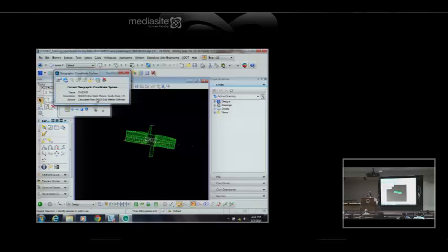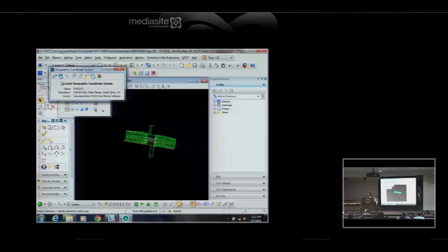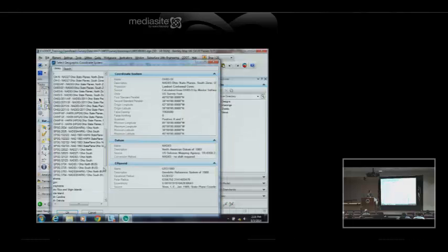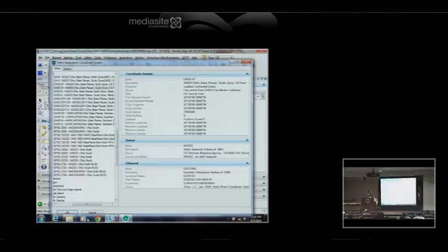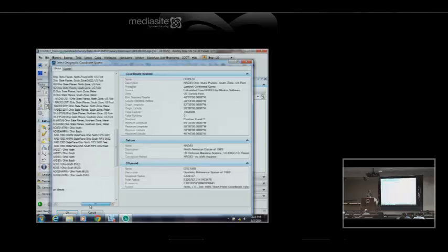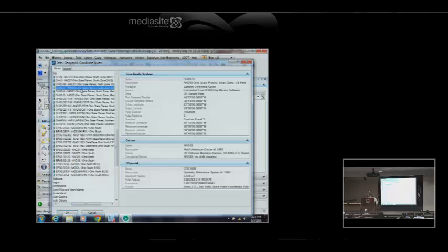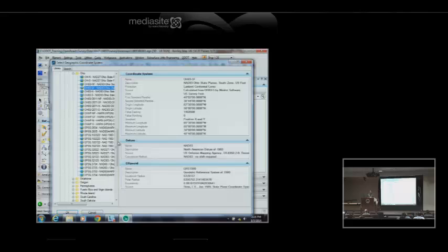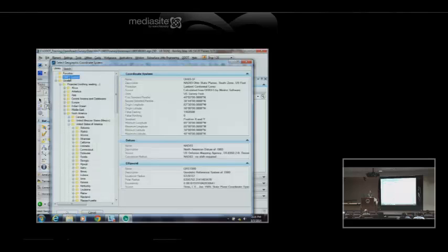Now, obviously there's more zones than that. So if I go in here to select a system from the library, there is the list of different coordinate systems that are available for Ohio. There's quite a few. That's the active, the NAD 83. Okay, so if I want to put this on ground coordinates, I'm going to copy this system, and with the project configuration that I have running, I see a folder for custom. Again, and I'll paste that in there.